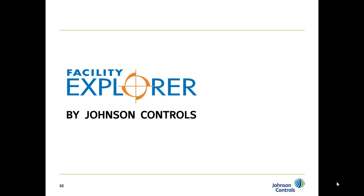In summary, Facility Explorer is well suited for controlling and automating many different kinds of buildings and systems. Its three-tier architecture and modular components allow it to be applied to a wide range of projects cost-effectively. You can start with a small or simple system and then simply add components for a larger or more sophisticated system. And its advanced control capabilities can help reduce energy costs, improve comfort, and minimize operational and maintenance manpower.